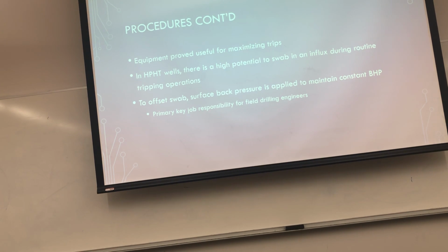The equipment proved useful for maximizing all trips. In high pressure, high temperature wells, there is a high potential to swab in an influx during routine tripping operations, but to offset swab, back pressure is applied to maintain constant BHP. And this is a primary key job responsibility for field drilling engineers.